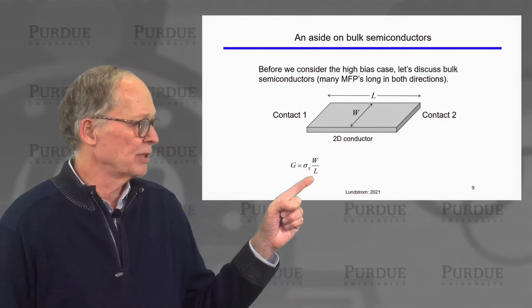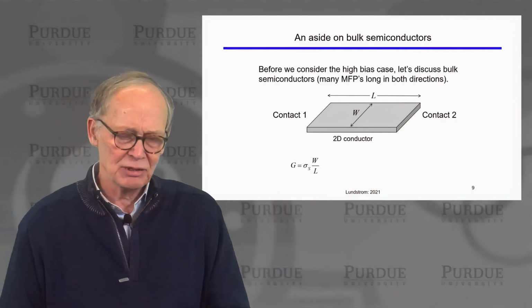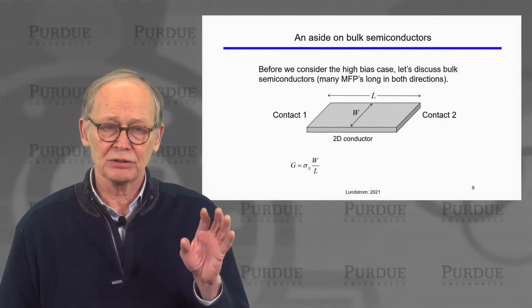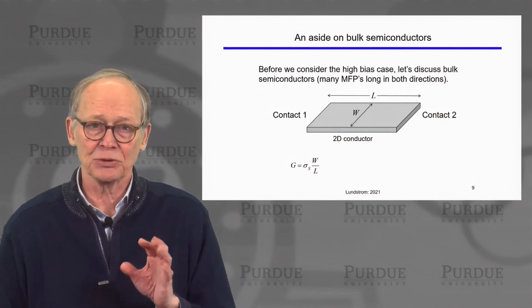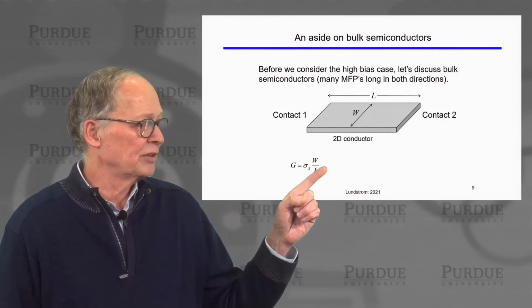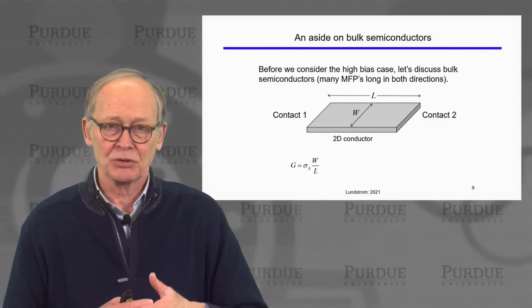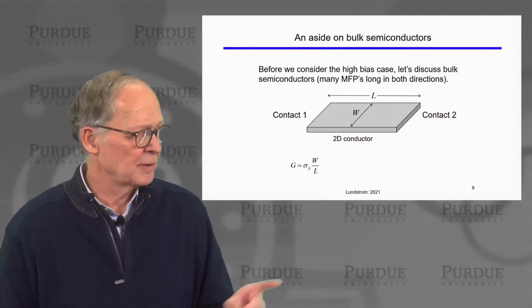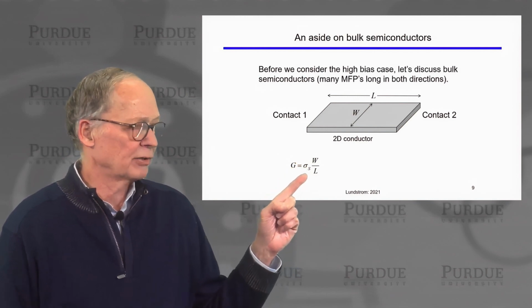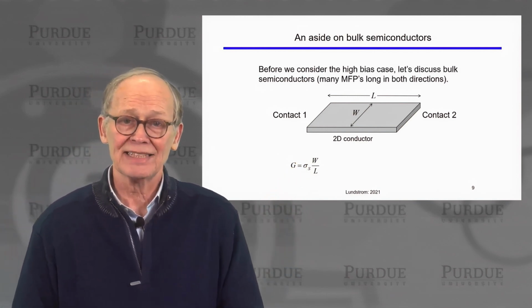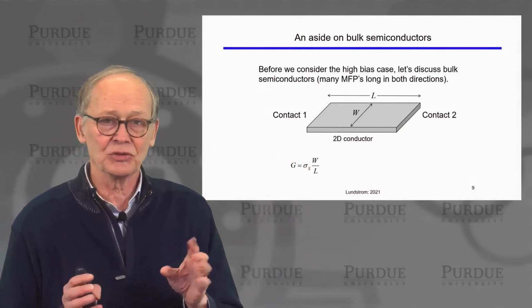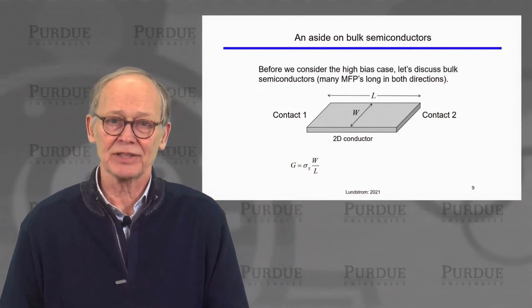We might do a measurement of the conductance, and you can recall that we would often equate the conductance to the sheet conductance in ohms per square times the width divided by the length. So the wider it is, the higher the conductance; the longer it is, the less the conductance. And the quantity that characterizes this two-dimensional material is the sheet conductance. If width equals length, I have 1 square, and the conductance is the sheet conductance.